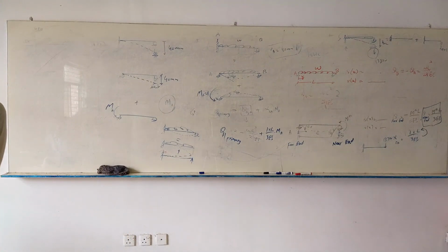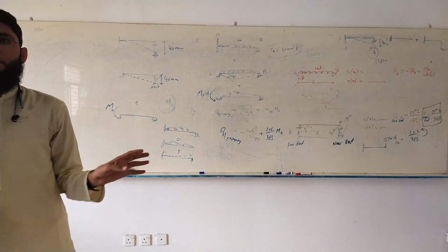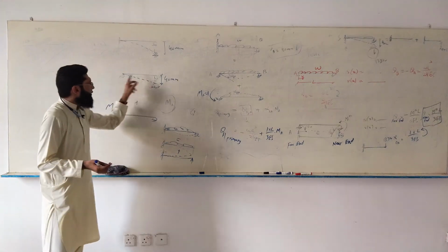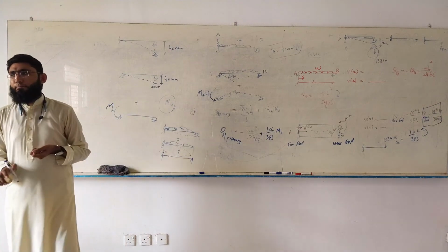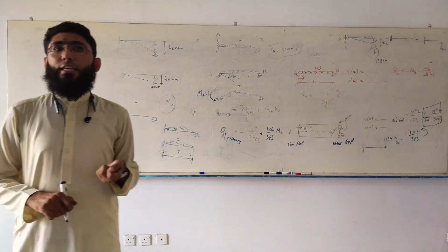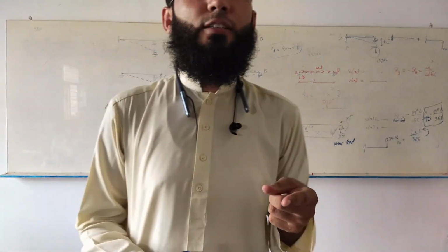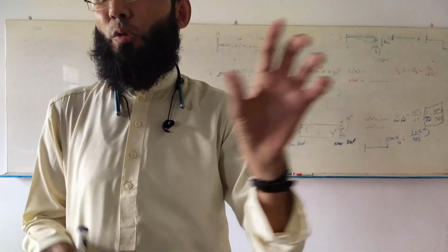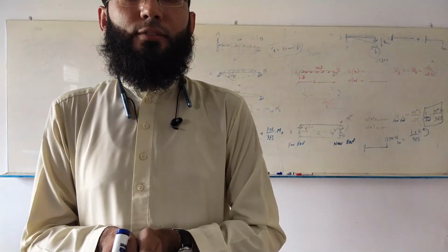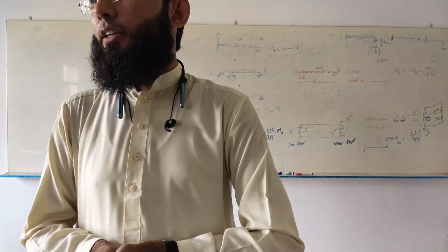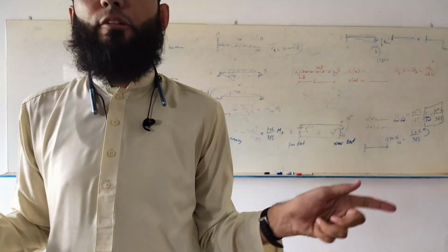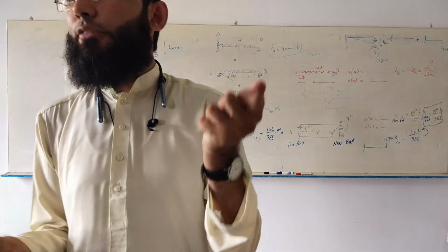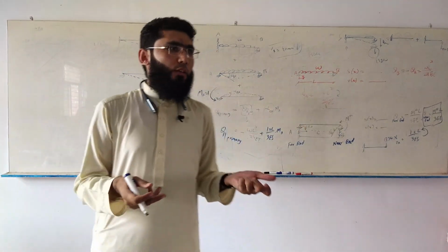Although it doesn't produce any reactions and internal forces. Why? This reaction is zero, this reaction is zero. There's no shear force, there's no bending moment. Why? Can you give me the right technical term? What would you call this type of structure? Determinate. A determinate structure does not experience any internal forces or any reactions when you impose displacements on it. It will just readjust its geometry, okay?